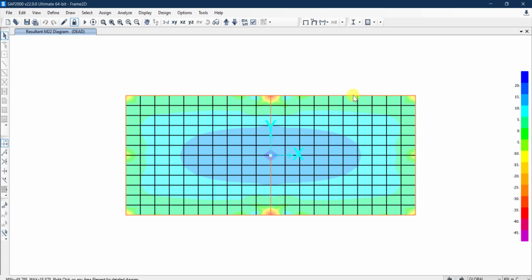So this is the 2-2 direction. This makes sense because my slabs here are two-way slabs. They are almost square in aspect ratio, so that's why you are getting significant moment in both directions. You will need those moments, of course, when you are trying to design for reinforcement, for instance, and things like that.